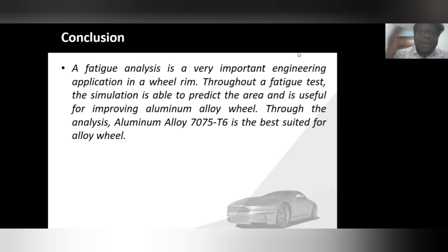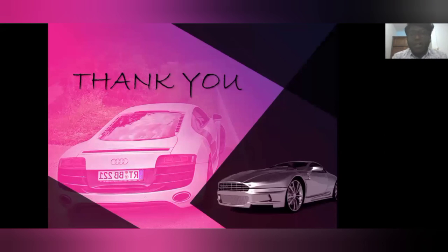Thank you, Muhammad Aiman bin Sheikh Muslim, for the good explanation. So we are almost at the end of this forum. We can conclude that fatigue analysis is a very important engineering application for a wheel rim. Through a fatigue test, the simulation is able to predict the area to improve in the aluminium alloy wheel. Through the analysis, aluminium alloy 7075-T6 is the best suited alloy for this wheel application.